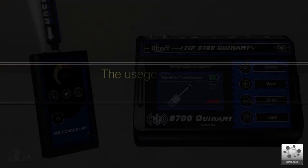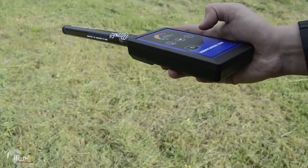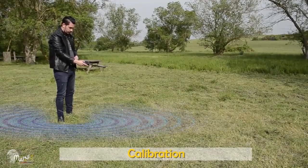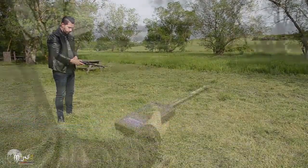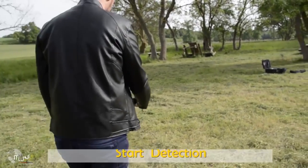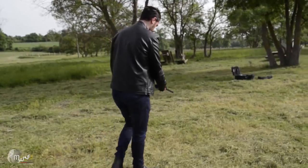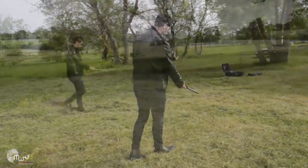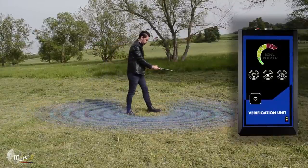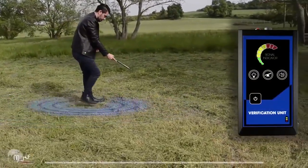How to use the ionic system? Hold the device, then calibrate the device with the soil by the calibration button. If needed, walk and direct the device horizontally towards potential targets. And if the device senses a target, gradually lower the device towards the ground to locate the target exactly. We'll notice the acoustic and lead indicators will gradually increase when closer to the target point.